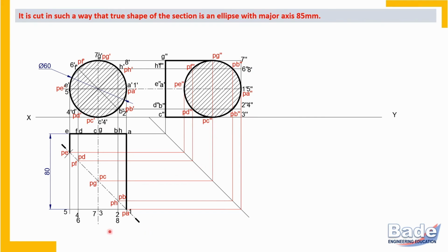Or you can say that the portion in which numbers are, that is removed portion. And base side portion, that is retained portion. So I have made a boundary of retained portion, and only boundary of retained portion dark. Don't make other generators dark. Take care. So sectional front view, sectional top view, sectional side view are over. Now one more very important thing you should understand here.